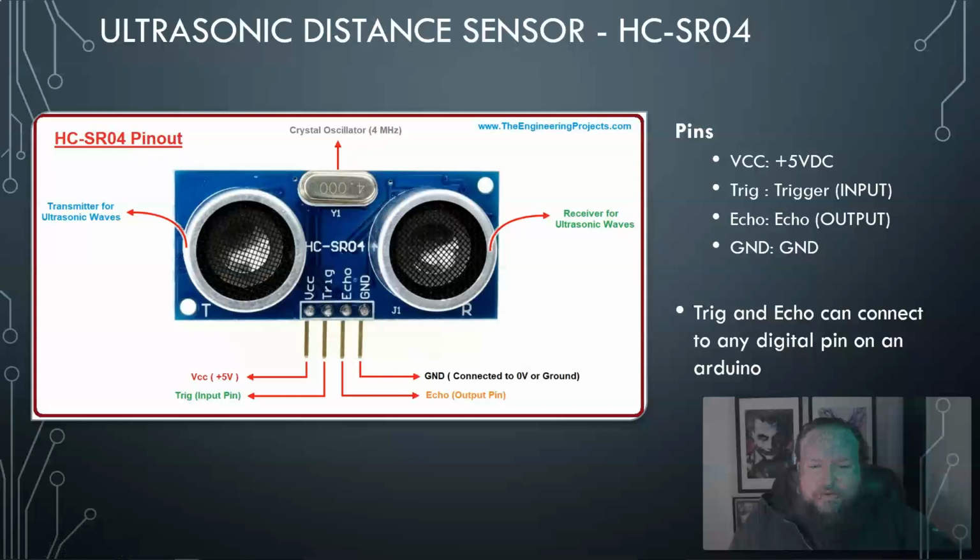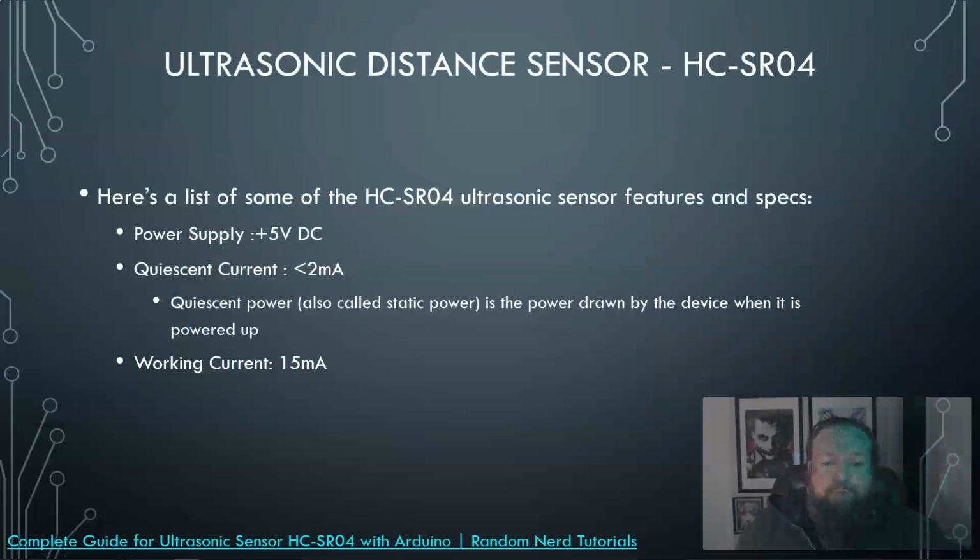And okay, I've got a trigger and I've got echo pins I need to connect. It doesn't give me more information to get to the Arduino yet, but it's the first step of understanding what the components are, what I'm working with. And I have to know how I face this, where it's coming out of, and what components have to be angled what way if I'm placing this into some kind of object. These are forward facing, one is going to beam it out like a speaker and one is going to receive it. This is the front side, so you can determine whether you have this at an angle, straight forwards, down, or upwards. It depends on your project and why you needed that distance information in the first place.